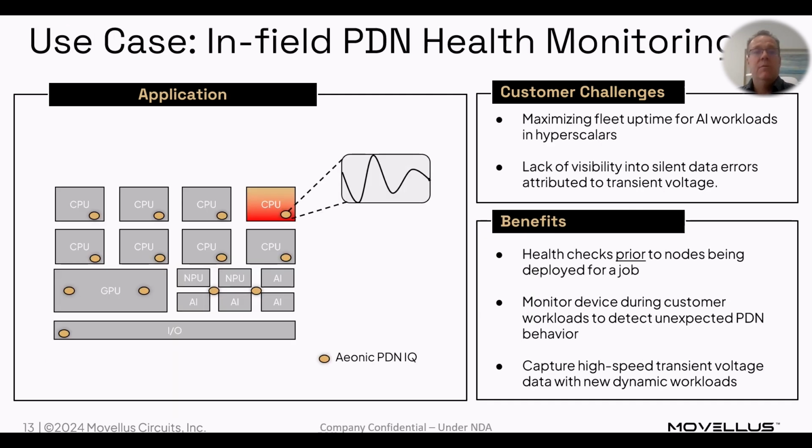And finally, out in the field, once you've deployed your chips into your racks, into your server clusters, you want to make sure you maintain visibility at the actual transistor level. Aging effects can come into play over hours, weeks, months, years, and being able to see a change in the characteristics at the transistor is very important. So electromigration effects, which could cause an increase in supply resistance, could cause larger voltage drops over time, and without visibility at the transistor level, you're not going to know.